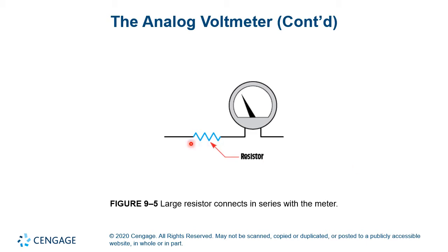Well, in a voltmeter, we know the current is going to be running through it. So what we do is build in internally a large resistor with a known resistance. It turns out the devices that we generally use, these coil devices here, actually all measure current. So what we're doing is limiting the current flow with a known resistor, and then we have a calibrated needle system here, a calibrated gauge. So when we measure the actual current, it's converted directly over to voltage.